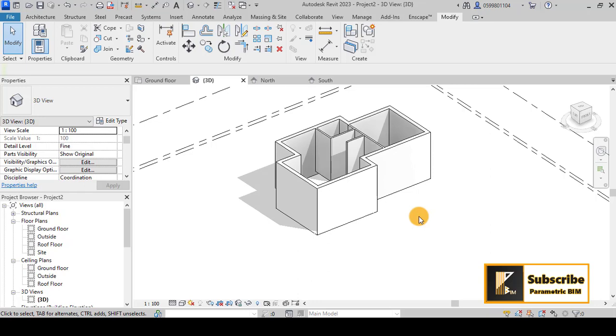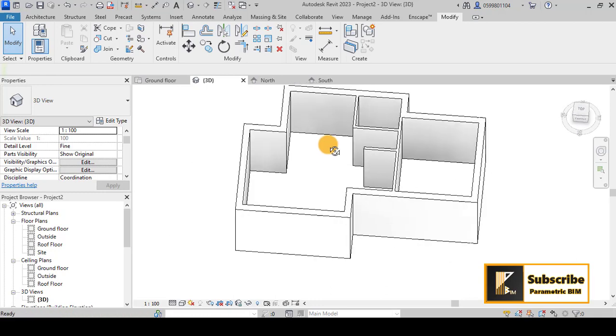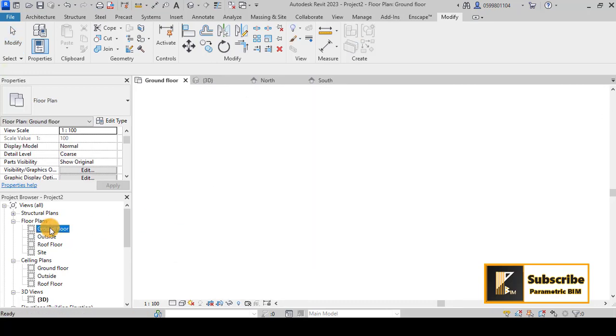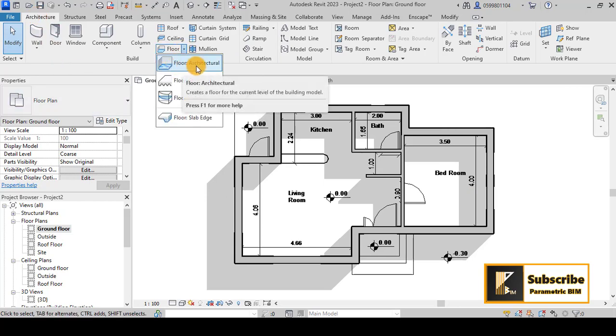Let's move to maybe the floors. So I will add the floor here on level 1 or the ground floor. I will go to ground floor, and now go to architecture, floor, and let's choose floor architectural.